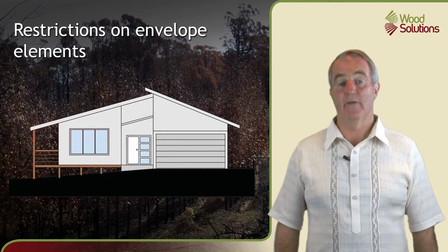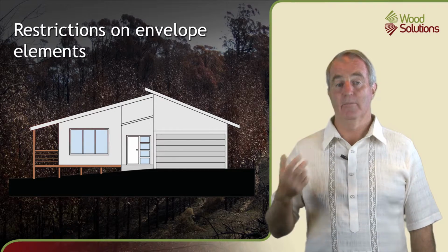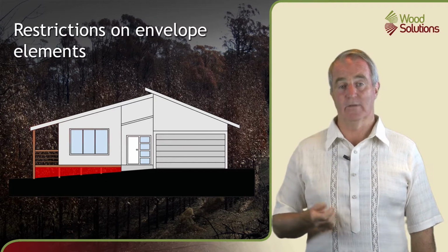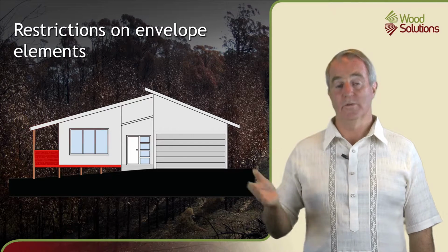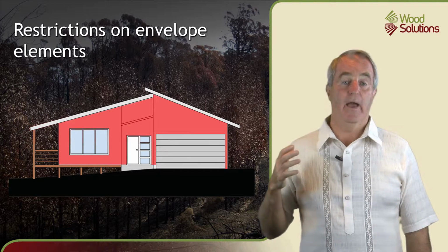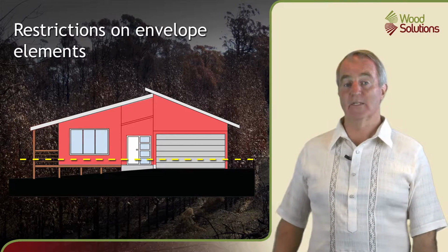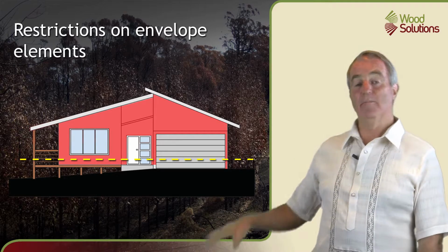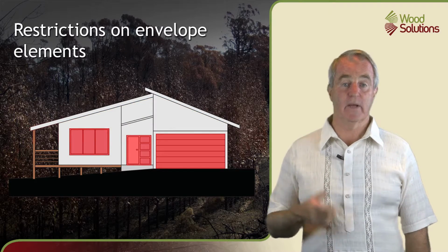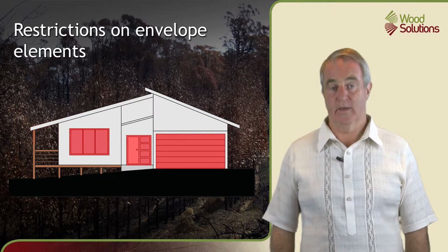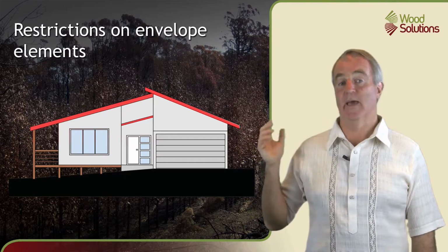External elements that may have material and construction restrictions on them under the standard include building subfloors that are either open or enclosed, stair decks and ramps, external wall surfaces. These have separate provisions for surfaces that are less than 400 millimetres above an external surface and those that are above this 400 millimetre line. External windows and doors, including the glazing, window frames and any fire shutters. And areas in the roof, including the roof surface, the soffits, the eaves, the fascias and the gutters.